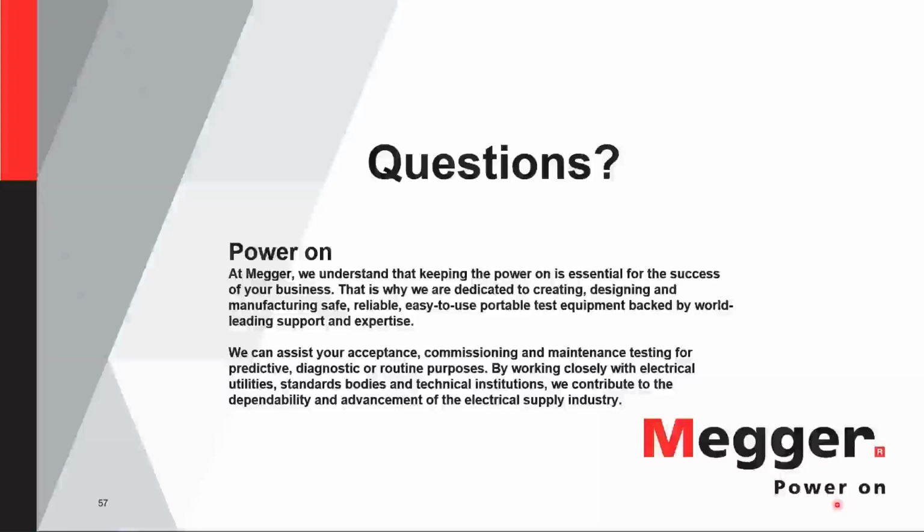Okay, thank you. Next question. Is there a correlation between breakdown voltage and the amount of water in oil? That's again a good question to ask, because there are different tests that are recommended. There is a ppm test or water in oil test, which is done by the Karl Fischer technique. You do DGA, and then you also do this dielectric breakdown. So each test has its own importance.